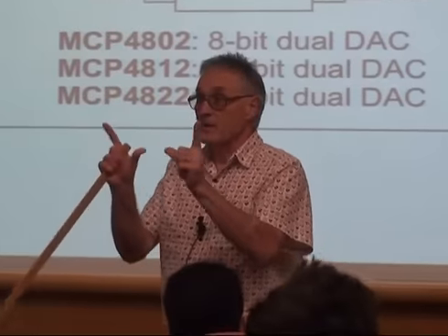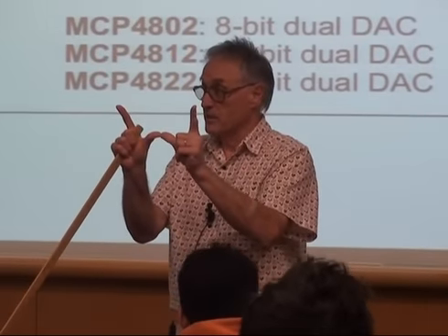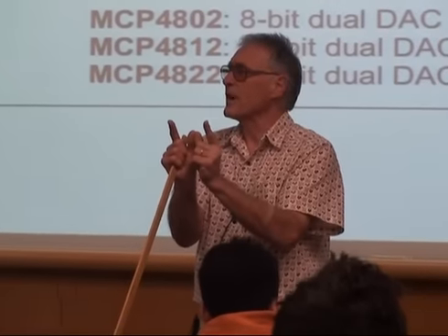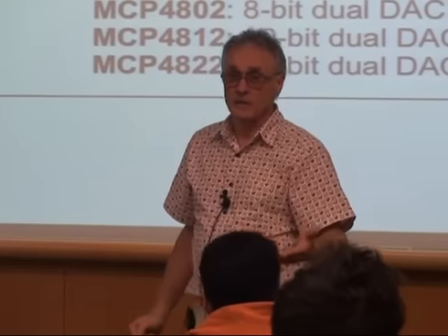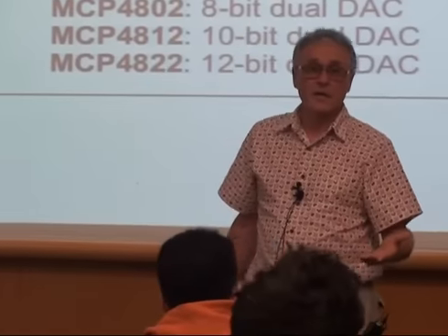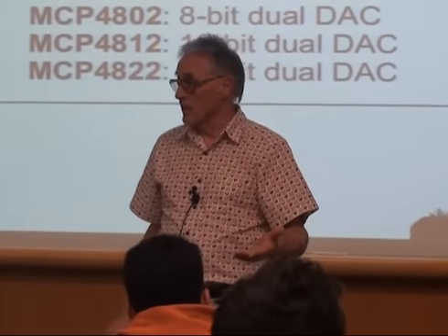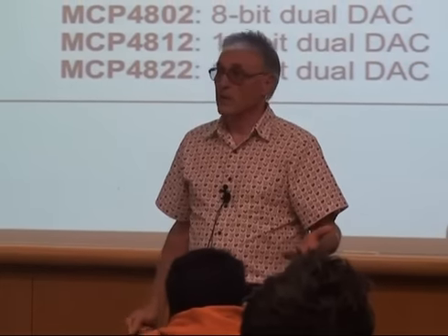Even if the power supply lead is only like 5 centimeters, it's still a nanohenry or so of series inductance, which sounds like nothing unless dI/dt is 10 to the 9th amps per second, in which case you have a 1 volt drop in the power supply.